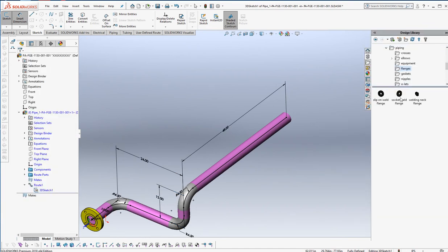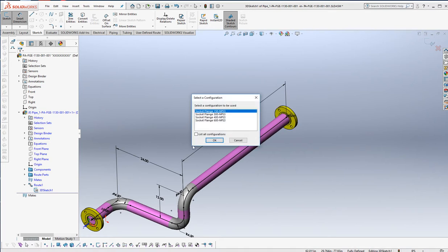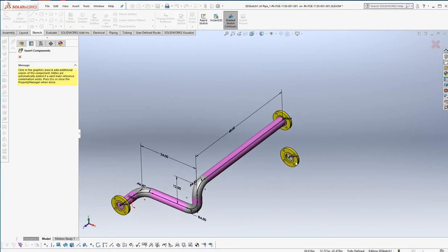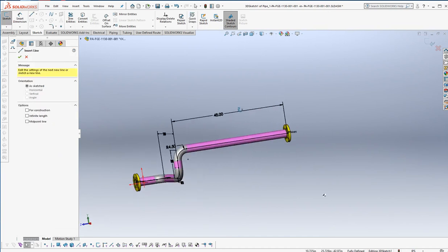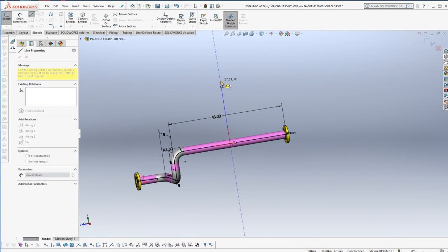And we could look at pulling out for a final flange. We pop it right there on that nubby. When it stops, you're good. And those are the size parameters. All right, so we hit escape. And let's draw an extension right here on this pipe. We can put it right there in the middle, but that might not be the middle because of the elbow. So we're going to draw it right here and then draw straight up.